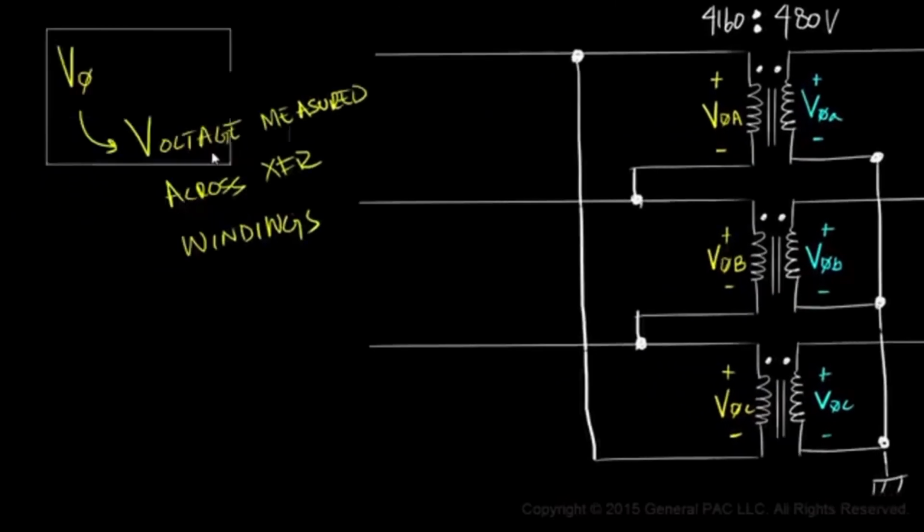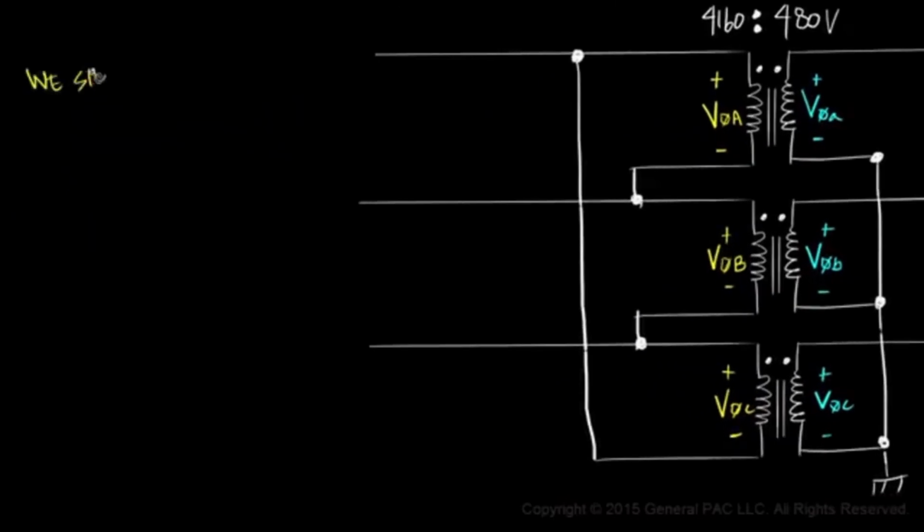On the primary side, where our transformer is connected in delta, we should expect the line to line voltage across line A and line B to equal phase A voltage. It is very important to visually verify this relationship to get an intuitive understanding.